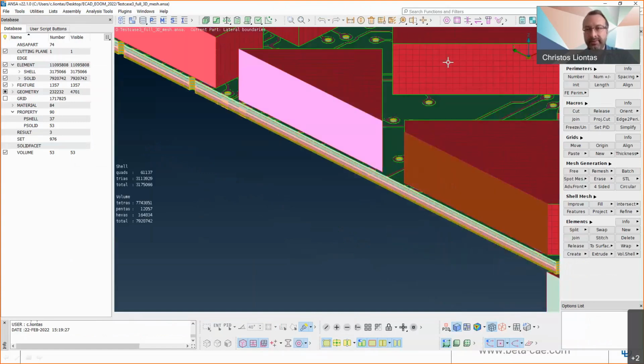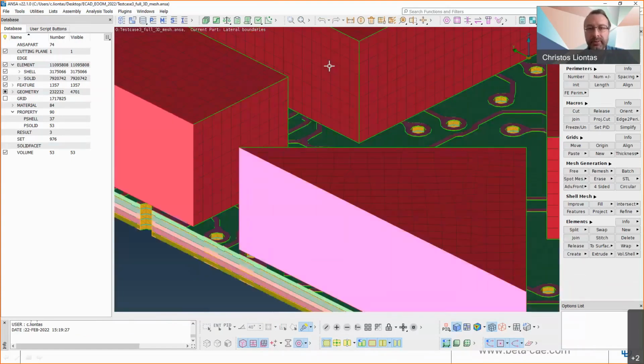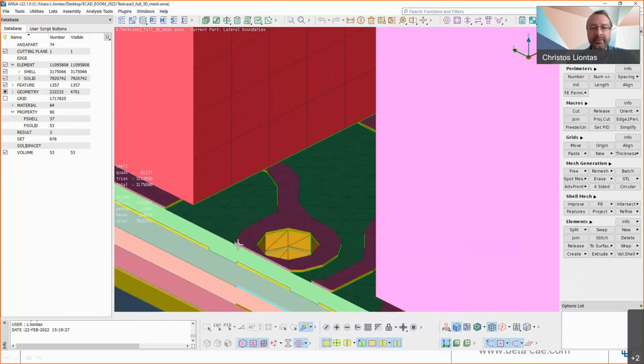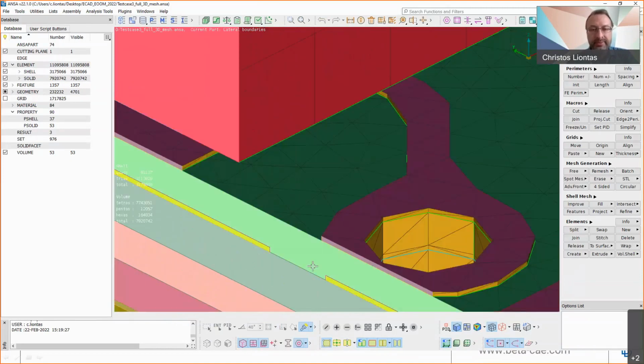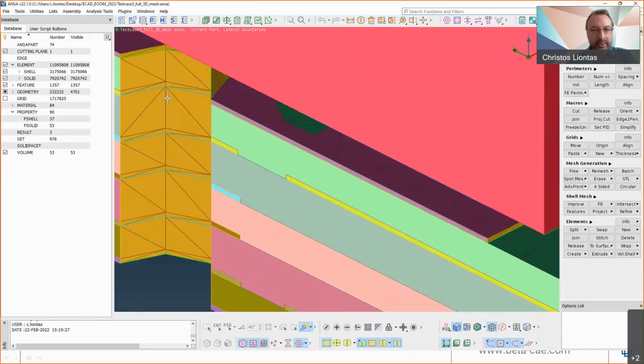So you can see here that the components have been meshed by map block, and all the rest has been meshed with either layered mesh for the thick metallization, tria mesh for the shell mesh, and unstructured tetra mesh for the volumes between the conducting layers. So here you can see that there is thick metallization inside these layers, and the vias have also been meshed.